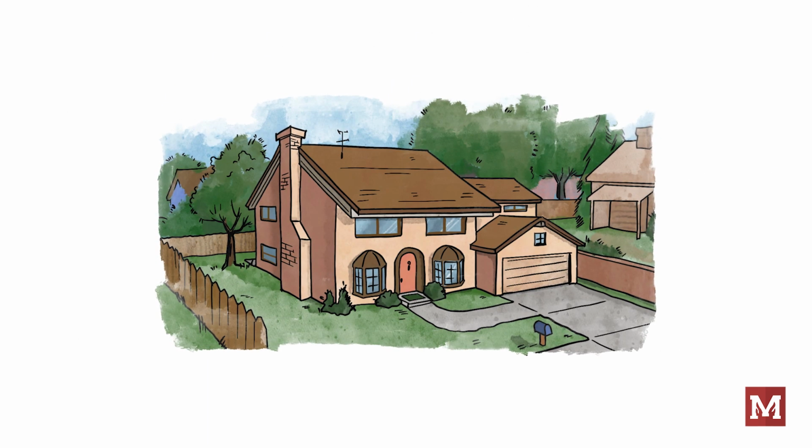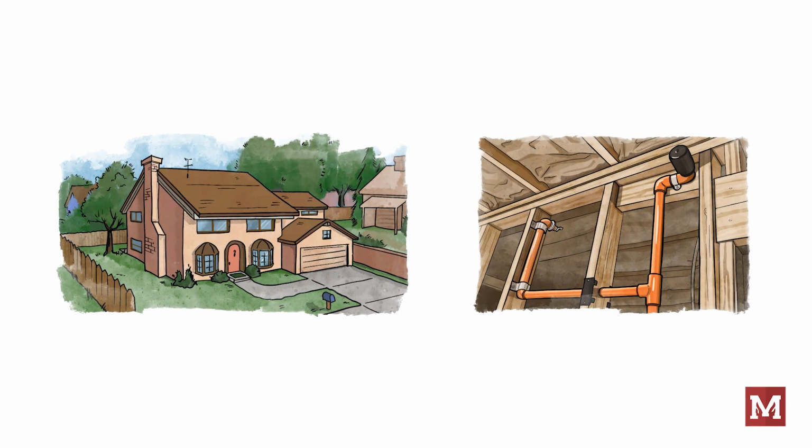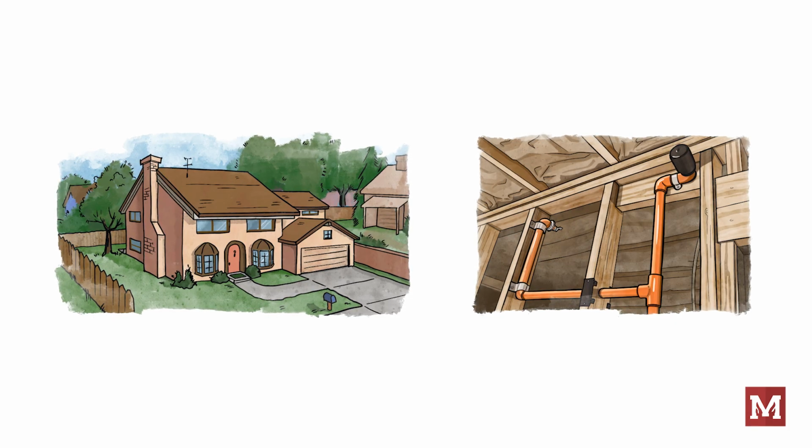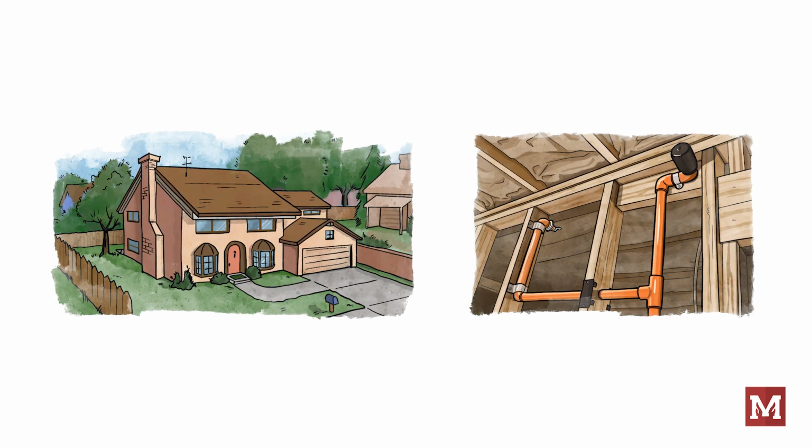In these spaces, we'll use copper pipe and copper fire sprinklers instead and just get rid of the ferrous materials to avoid all that. In hotels, motels, houses, and other residential occupancies, we'll find residential sprinklers. These are specific application sprinklers. They do have different deflectors, and they shape water differently than other sprinklers. They have their own spacing rules too. Residential sprinklers are designed primarily to wet the walls in a compartment during a fire. What this does is it maximizes the chances of a person surviving a fire who might be in a house or inside of a dwelling unit.